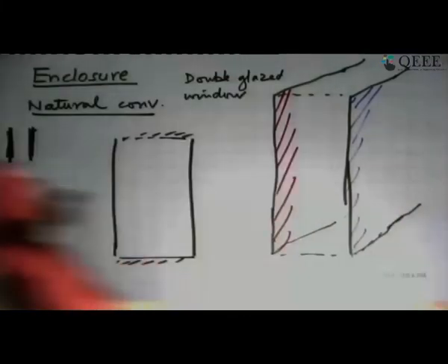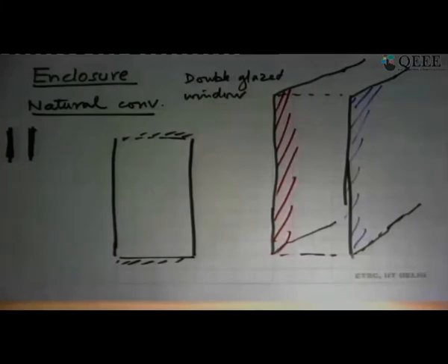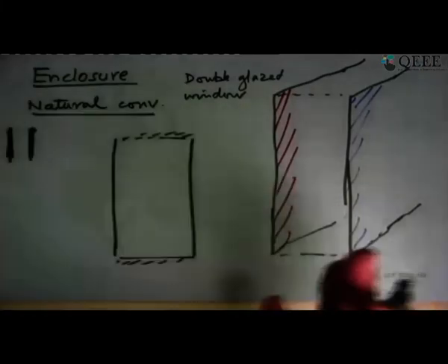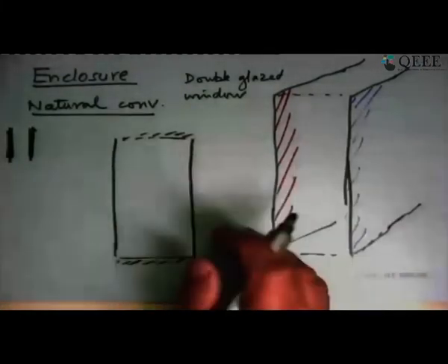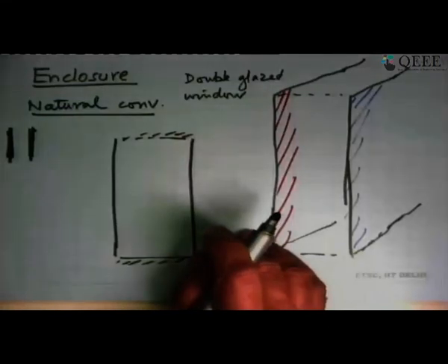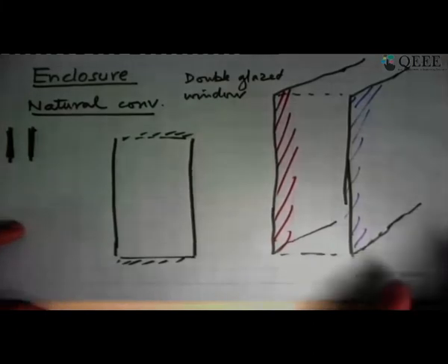The same thing can be done with walls also. So you give an air gap between brick layers, and you get very good thermal insulation, not just for cold climates, but also equally justifiable for hot climates. If you see traditional architectures in very hot climates, they have exploited this idea again and again to make much more comfortable conditions inside than when it is very hot outside.